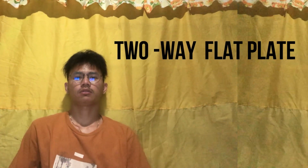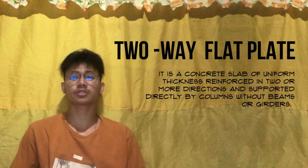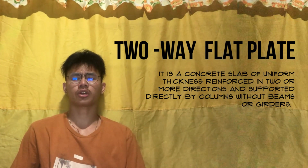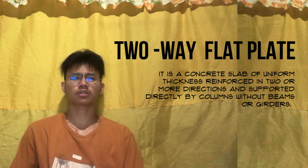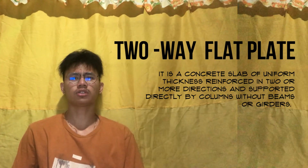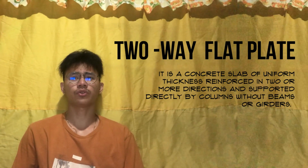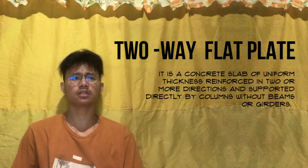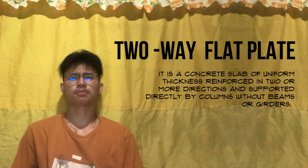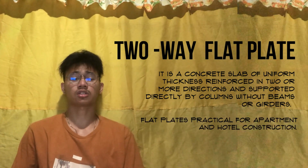Two-way flat plate. A flat plate is a concrete slab of uniform thickness reinforced in two or more directions and supported directly by columns without beams or girders. Simplicity of forming, lower floor-to-floor heights, and some flexibility in column placement make flat plates practical for apartment and hotel construction.